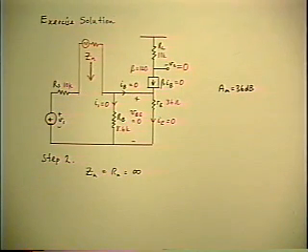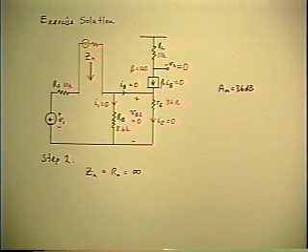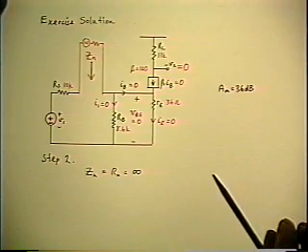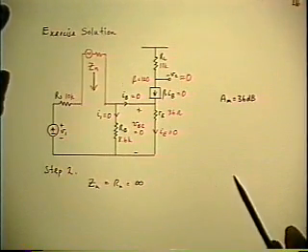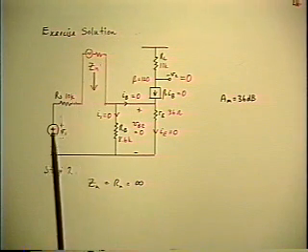Now, in this case, you can get the same answer by an instant shortcut. Do you see what that is? How can you tell immediately that there's 0 current in the second source? Because the two sources are directly in series.